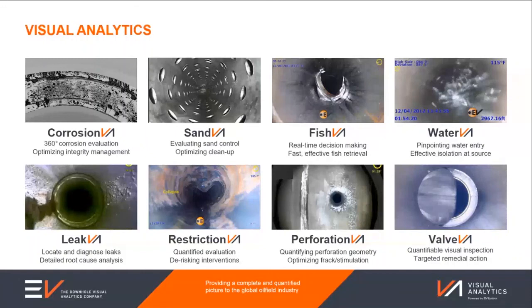But if, on the other hand, you have a particularly difficult situation where the risk of anything protruding from the tool string is a risk, we'll actually run without any centralizers or very, very simple standoffs if required. Examples of this may be if you've got something like a subsurface safety valve, or even a formation isolation valve that you're not sure whether it's fully open, partially closed, and you want to avoid getting stuck in it. We'll run slick, we'll come down through the upper completion, and in real time look ahead of us to try and avoid any incidents or accidents.